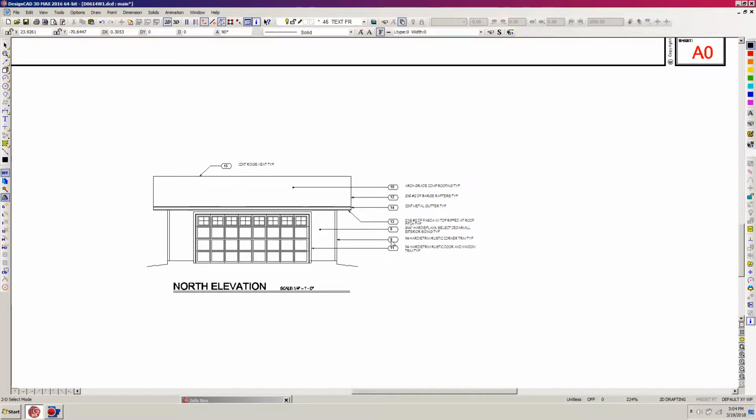because we're going to be using these on the other drawings. So I'm going to select this whole enchilada right now, the sheet notes and the sheet note boxes and their text, and then I'm also going to go out of orthogonal mode. I'm going to go out of point select mode so that I can hold down Shift and select this additional sheet note and its sheet note box, and click back into point select mode.